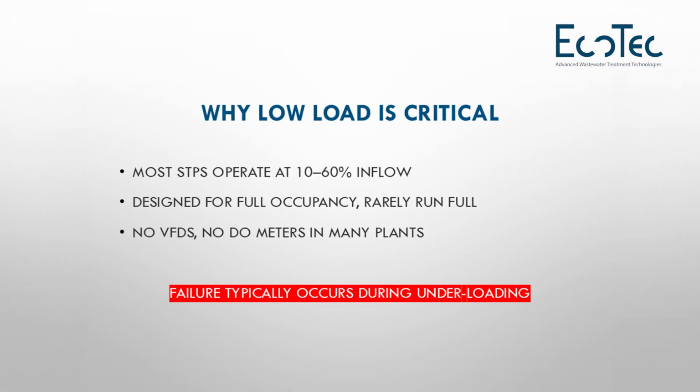Let us face the ground reality. Most sewage treatment plants, be it ASP, extended aeration, or MBBR, are designed for full occupancy. But how often are these buildings fully occupied? Almost never.